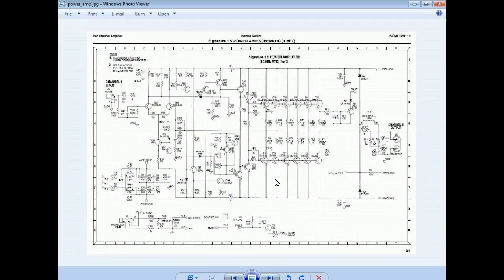By the way, what's the function of the resistors? Well, these are little old tiny resistors. I can't see the size of them. But what happens if these things are not perfectly matched is that one of your transistors would try to take the load. But if it tries to take the load, its emitter resistor is going to try to conduct more current, but the emitter resistor won't let it, right? You all understand? So these guys right here are in there to balance the load. These are all hooked in parallel. The only difference is that each one of them has its own resistor. And this is one channel, by the way.